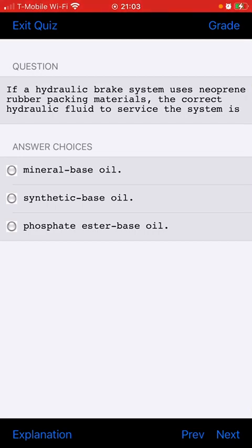It states, aircraft pressure fueling system instructional procedures are normally placarded on the flow control panel access door, lower wing surface adjacent to the access door, or aircraft ground connection panel. What are they asking me? Aircraft fuel pressure system, fuel control panel access door. I think it would be at the fuel control access door, the system that tells you how much pressure can go into the system without causing damage.